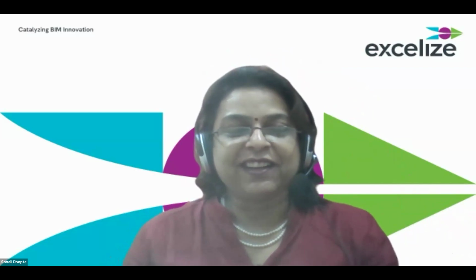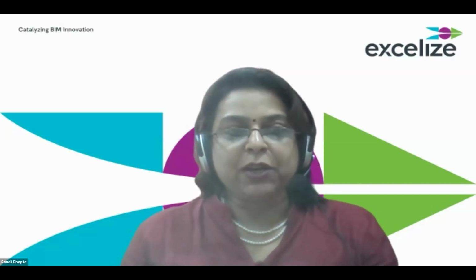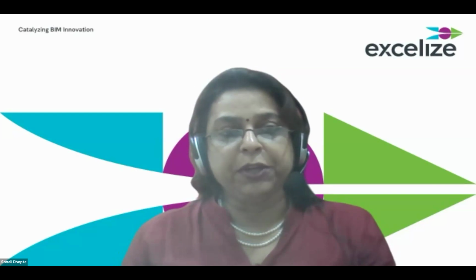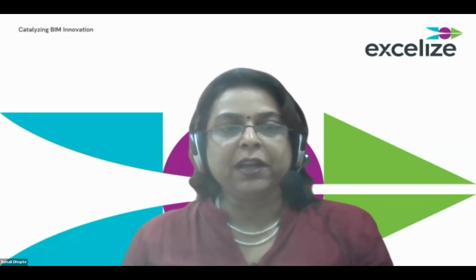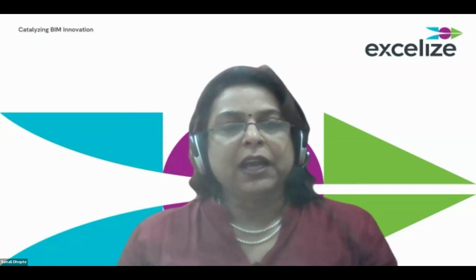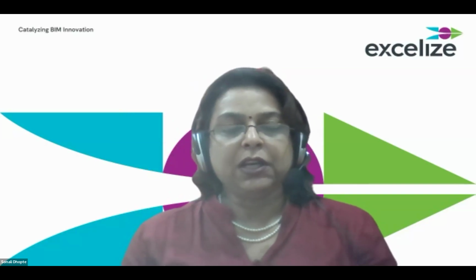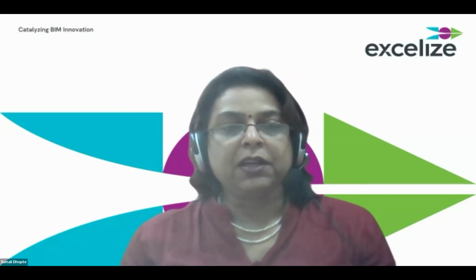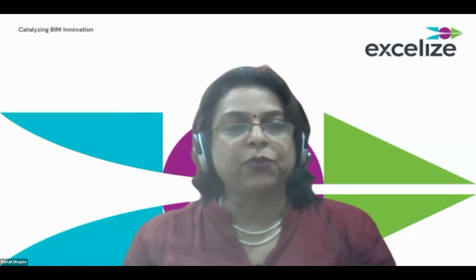I'll take one last question now, and that question is, is there any plugin that can be used for checking statutory bylaws or fire and NBC norms? Not for India's bylaws, but there is a software called Solibri, in which you can set the bylaws that you need. Programmatically no, but it has fields that let you set it. Then you import your model into that software and it will check for bylaws. Solibri is called a code checker. It has some countries' codes already programmed into it, and then you have the ability to program what you need for India into it.